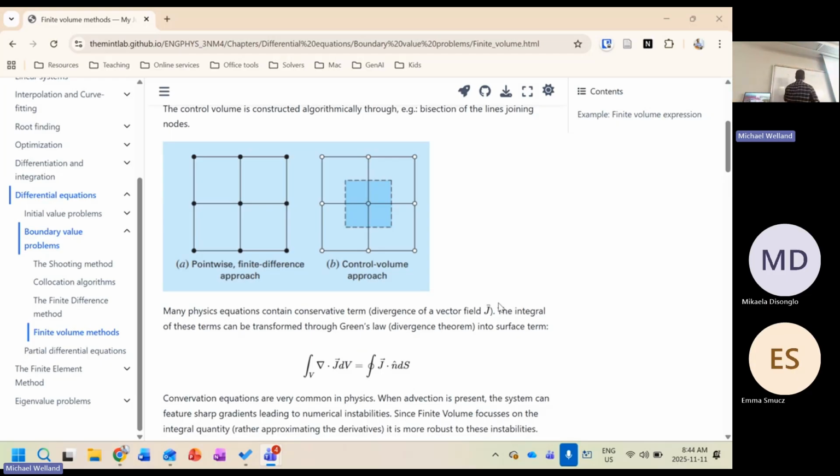What it's going to do there is, you have some pipe or something like that, and your mesh is going to be constructed nice and tight and refined near the wall, and then much larger further off. And that's because typically you would have some kind of no slip condition, right? So your velocity profile would be 0 here, and then kind of up higher as you get into the middle there.